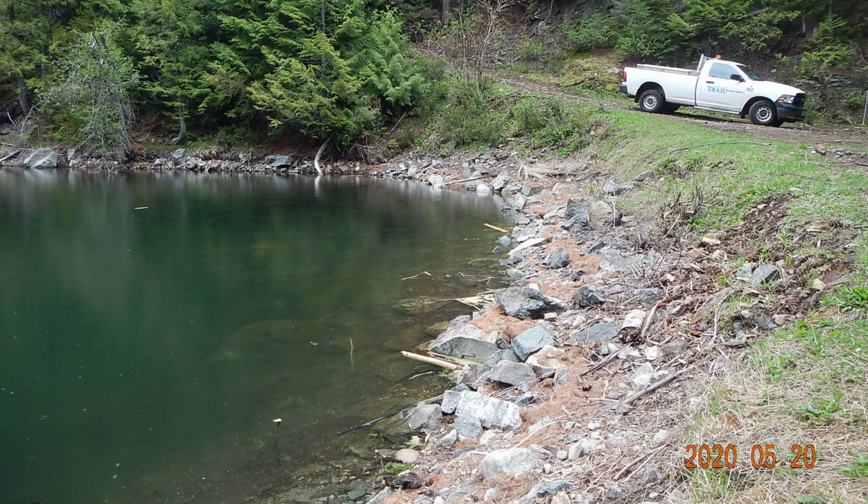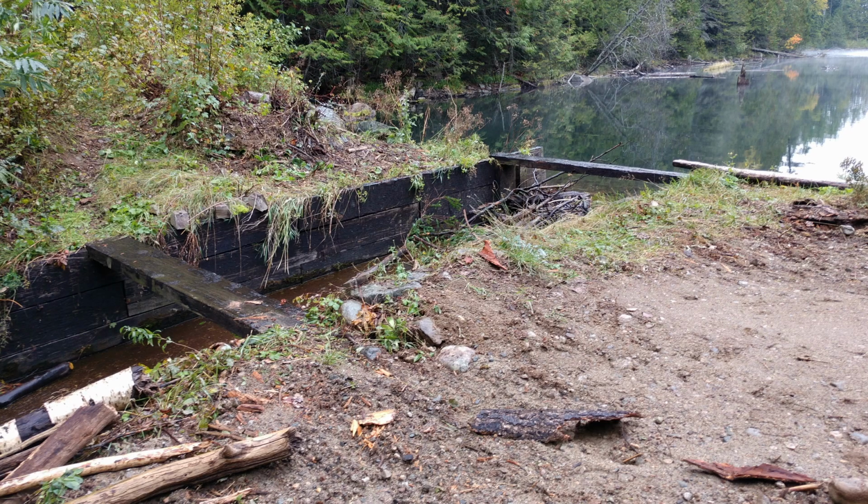The dam was armored with rock in places so that wave action would not cause damage to the dam and to help protect it from muskrat and beaver burrowing activity. An emergency spillway was built to carry overflow from Violin Lake into Goodeve Creek. The spillway was 11 meters long and 2.4 meters wide.